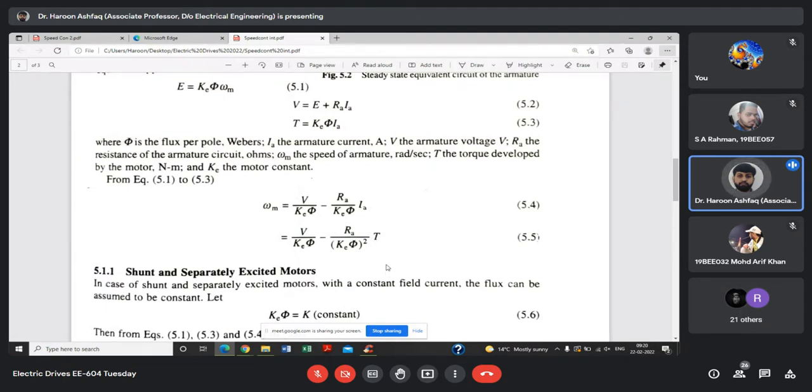So you reach to this point. So now you can vary V. Now V cannot be increased beyond the rated value because there are obvious reasons for it. जो आपके पास हैं कि you have a system that is designed for particular values of power, V into I, that is P. Also, the insulation systems are also designed to cater those values. So V is never increased. So V can always be decreased.